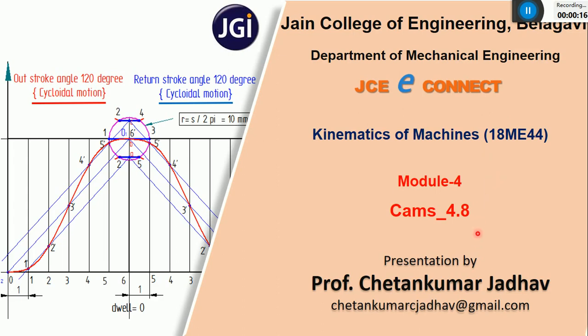This is your class number 8 of module number 4 of your subject kinematics of machines. In today's class, we are going to solve one problem on a roller type of follower which is having a cycloidal motion during outstroke as well as during return stroke. You can see over here, this is the displacement diagram for a roller type of follower in which the type of follower motion will be of cycloidal type. For both outstroke and return stroke, the type of follower motion is cycloidal motion.